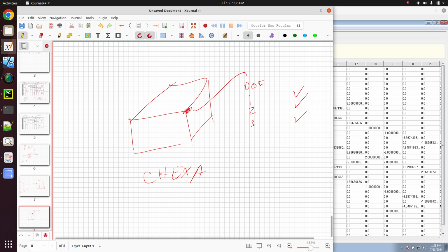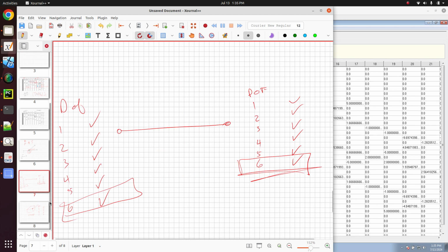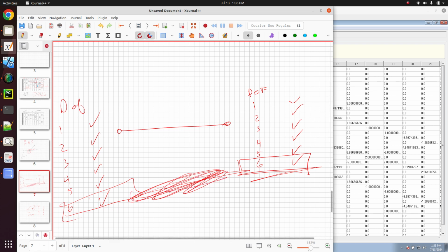So here, this element does supply stiffness along the translation degrees of freedom, but for the rotations, it adds no stiffness. There's zeros. So if we go back to the beams, the beam is adding rotational stiffness for the 6th degree of freedom, but there's something a little weird or off about that degree of freedom.